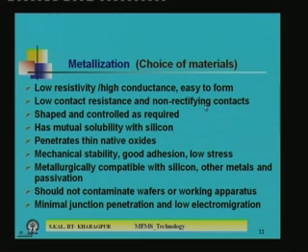If it is a rectifying contact, then at the contact position you are unintentionally fabricating some diodes, which is a metal semiconductor junction diode. So, metal semiconductor junction should be ohmic for ideal contact. Okay. So, all the metals with silicon will not give you ohmic contact, some of the metal combinations with silicon give rectifying contact. So, when you select a material, you have to take care of that aspect. So, the contact must be ohmic, so that you can choose the proper material.